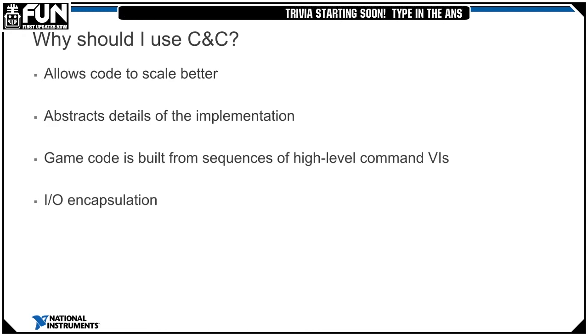The commands themselves are the VIs that update set points, perform any numerical scaling or mapping between engineering units and mechanism units, or offer synchronization options. If physical changes are made to the robot, such as adjusting a gearing ratio, these changes can be made to just a couple of VIs to implement this change across your entire code base.